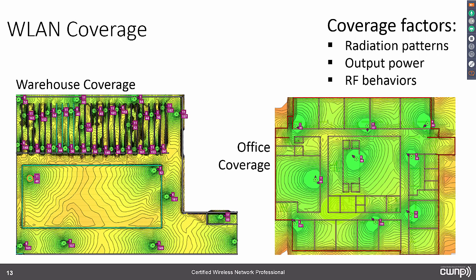That is done through modeling with tools like Ekahau, Survey Pro, IBWave Wi-Fi, and so forth. Tamosoft has a Tamograph tool for survey as well. So those kinds of tools are going to tell you that, and actual real site surveys where you go in and actually capture the actual RF energy information in the space. That's going to show you what really happens.